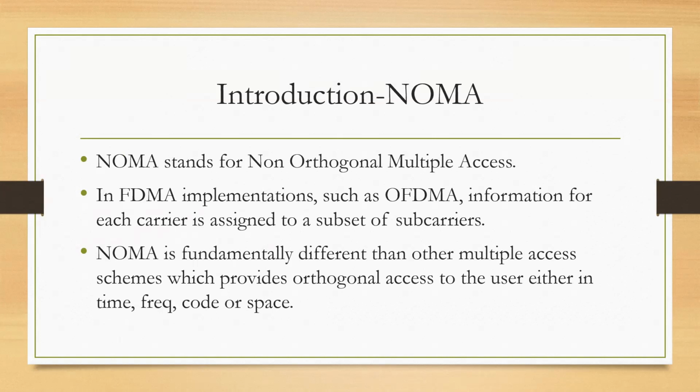Now, what exactly is NOMA? NOMA is a multiple access technique, and NOMA stands for non-orthogonal multiple access. Generally used multiple access techniques like FDMA or TDMA, which stand for frequency division multiple access and time division multiple access, use techniques like frequency multiplexing and time multiplexing in order to achieve orthogonalization between the signals. But NOMA is fundamentally different from all these techniques.